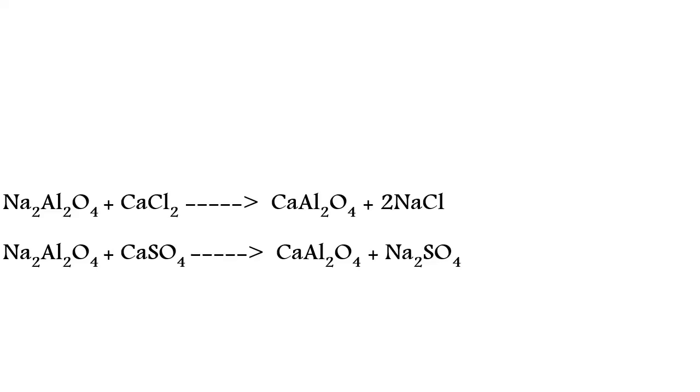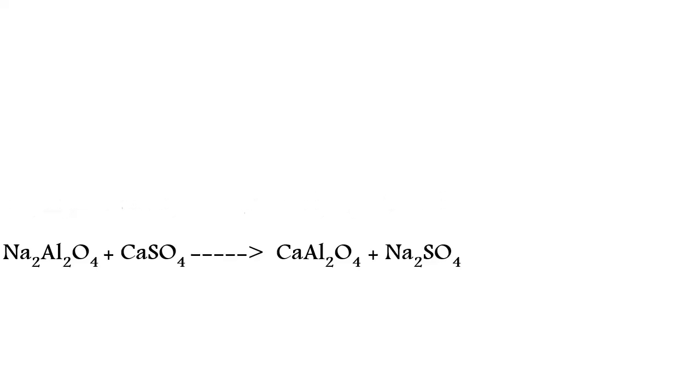In some advanced treatment plants you can use sodium aluminate. Otherwise, alum is good for us and universally accepted. Then you need to do the comparison of alum and iron salts. The general point here is, alum is used for water treatment and iron salts are used for sewage treatment, and the other 3 to 4 points you do on your own.